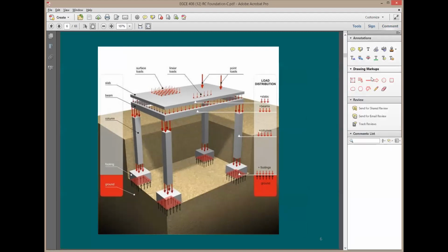So again, here's one beam, and here's the other beam. It means this support, which is a column, supports both of these 2 beams. And whatever reaction that you find from the right beam and the left beam, you just add them up and then you put it to be supported by the column. Now you should be able to design the column here at the bottom of it, right? You say, here's the total column load.